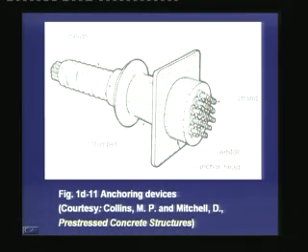Then there is this conduit in the shape of a trumpet which gets attached to the sheath of the duct. The strands are passed through this sheath and the anchorage block, then they are fixed to this anchor head by the wedges, individual wedges for the strands.